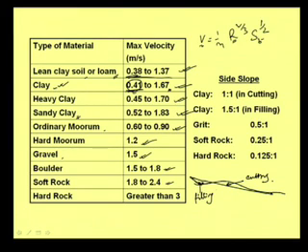So for the portion where we have cutting in clay, there we can go for a side slope of 1:1. But in the filling portion, we should not go for that sort of steep slope, we can go for 1.5:1. Then of course, when it is grit, we can go for 0.5:1. And if it is soft rock, we are talking about cutting soft rock, then it is 0.25:1. That way it is increasing. For hard rock, we go for 0.125:1. And in fact, for hard rock, we can go for zero slope also. I mean, zero slope means it is vertical.